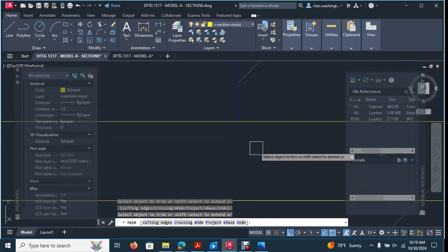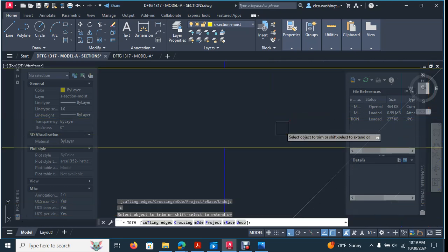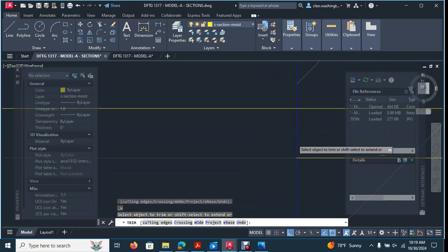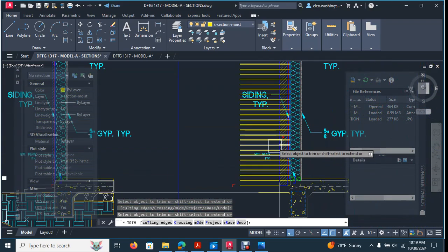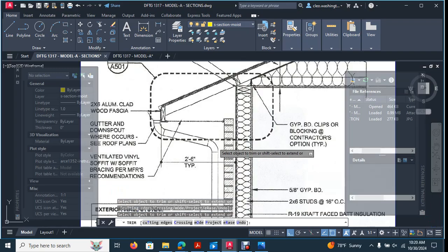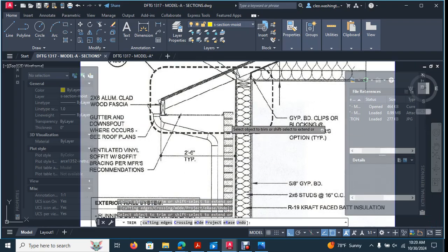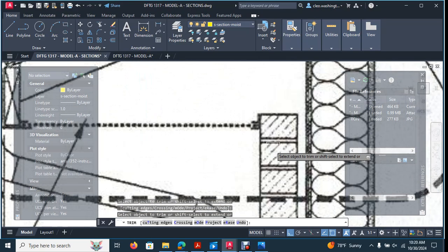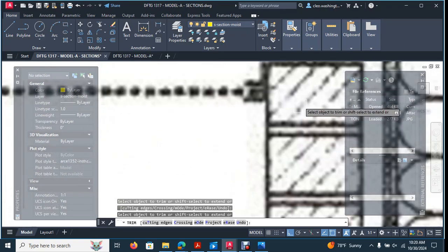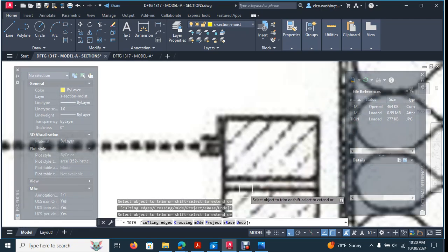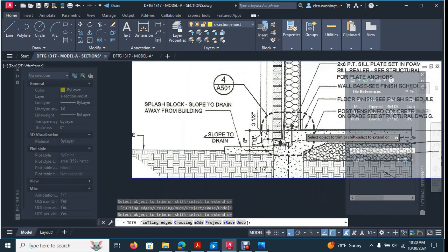So what I'll do is I'll draw this one for you guys, and then I'll actually let you guys note this one up just like you noted the other one up, based off of the notes that are in this drawing right here. Okay, you see how these bricks stop and you have a whole brick? Because it actually courses. It has the brick size and it has the 3/8 inch mortar joint. So we're doing the same thing here.